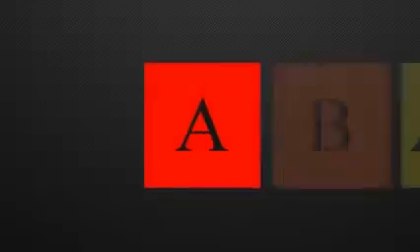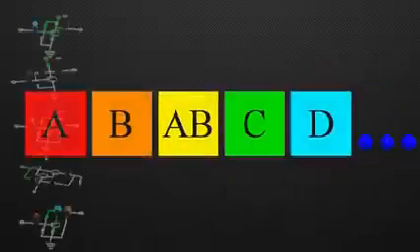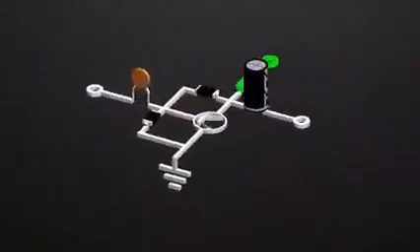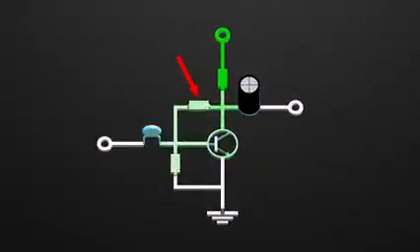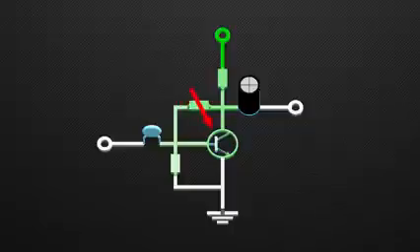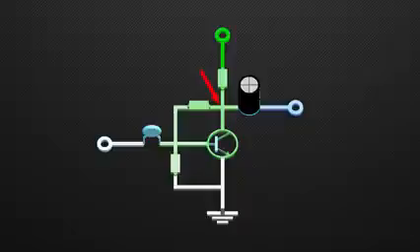This is the simplest type of Class A amplifier circuit. We can add more components to it for improvements. In this circuit, the biasing resistor is connected after the RC. When the input voltage increases, the base current increases, which increases the collector current, and the voltage at the output falls. This also drops the bias voltage, thus the base current drops, collector current drops, and the voltage at output rises. This resistor now provides the negative feedback, and limits the gain of the amplifier.